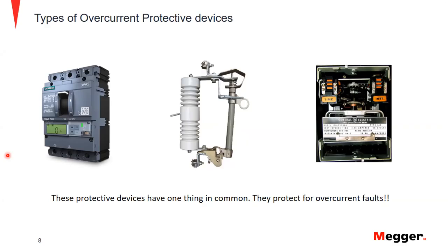And then the third thing we have is the electromechanical relay. What this guy does is he actually senses fault conditions by using CTs, or current transformers, that are either coming from a breaker, transformer, or even some external CTs that are actually in the yard. So when the predefined setting of the overcurrent relay is exceeded by the tap value, the disk will move and it'll close a set of contacts which will attach to the circuit breaker trip circuit, and therefore it'll open the associated breaker that's tied to the trip contacts of the electromechanical relay.